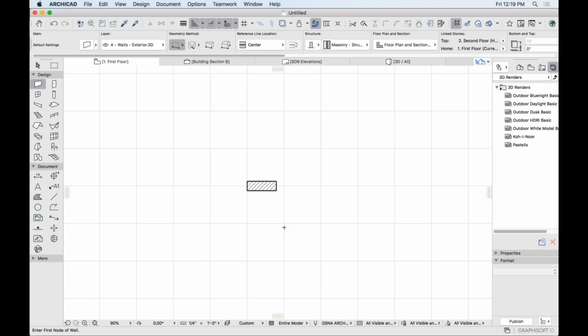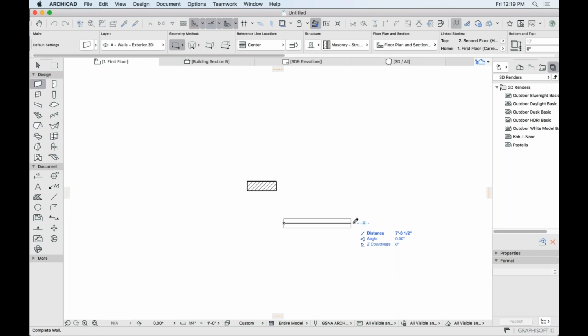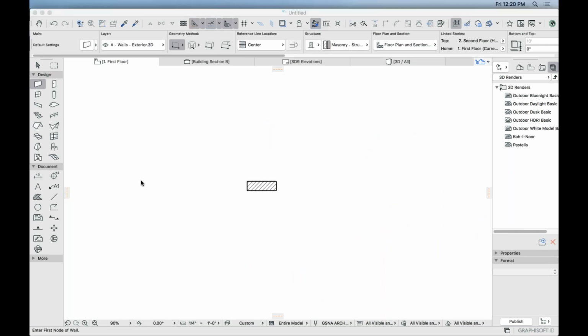Another thing that will restrict you from getting angles, if you are feeling restricted, is that if you hold the shift key in the horizontal or the vertical, then you're locked in as long as you hold that shift key. You're holding that shift key, I can move my cursor all over the place, but it's only going to go up and down, or side to side, or if I happen to snap it on the 45, it's only going to go along that 45-degree angle. So maybe that's what's happening. I think that there are a lot of conditions which could lead to that, so we probably would need to look specifically at what's going on there.